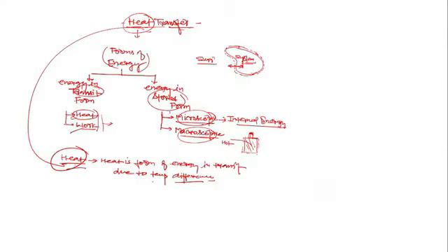And we should not say, let's say, 120 kilojoule of energy is there, so this 120 kilojoule is heat. It's not correct to say 120 kilojoule of heat is there, because heat cannot be stored. Heat is a form of energy in transit. Is this clear? We should say 120 kilojoule of energy is there, because once the energy gets transferred, that is called either heat or work.